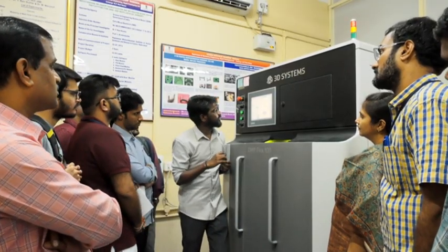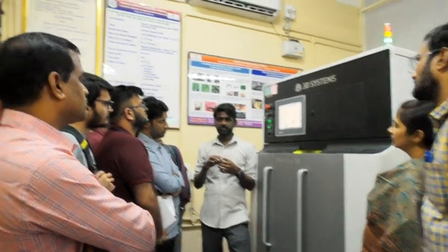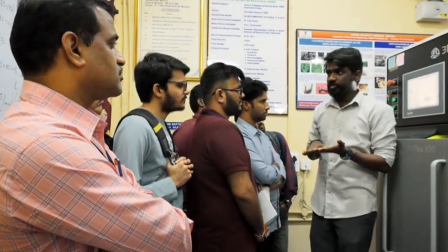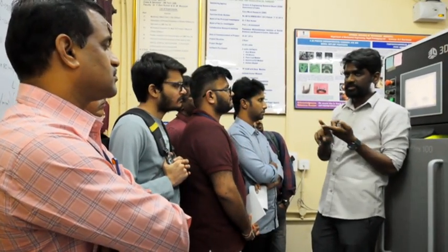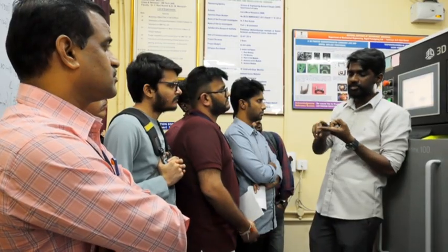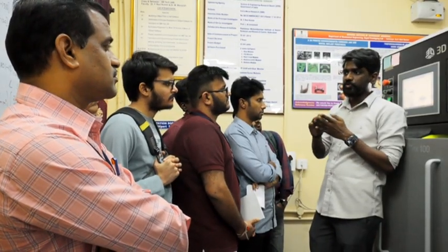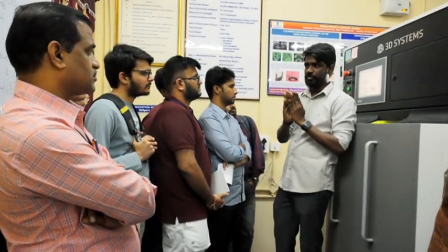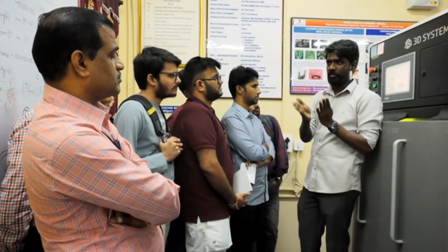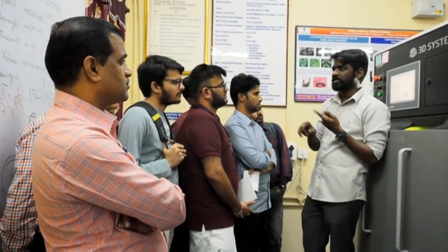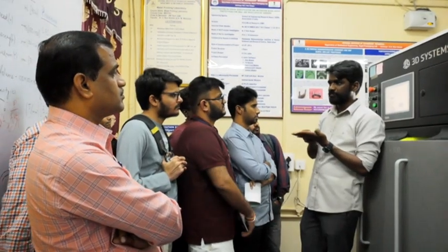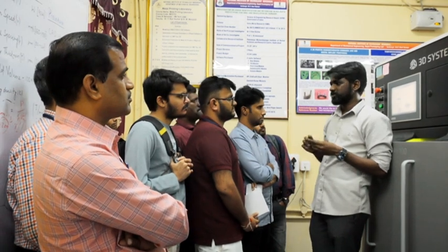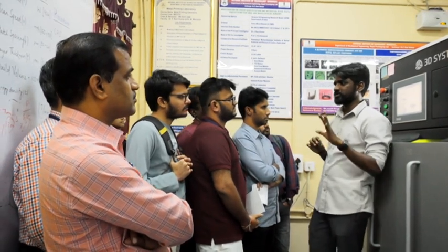Right now we loaded around 2 kg, I think. Why? Because initially some sintering will come. Before that you have to do some remelting. Why? Because they are using a substrate, and it should be attached to the part. Sometimes it is going to detach or warping will come. In order to remove that problem, we are doing remelting, means double times. Then some part will get attached to the surface. Those parts we can easily remove by wire cut, so that is not required. That's why we are following 10 layers mostly.